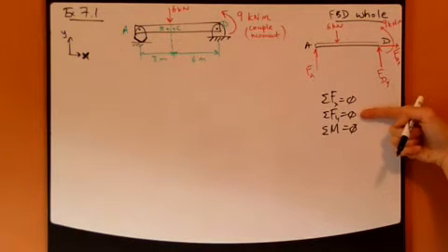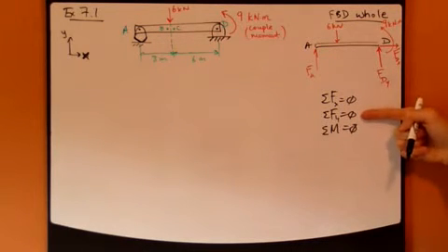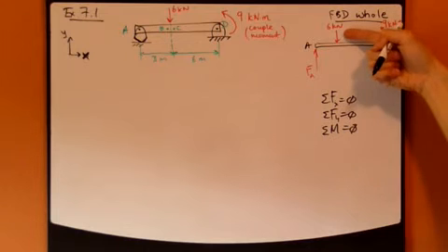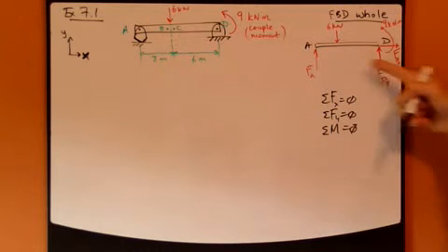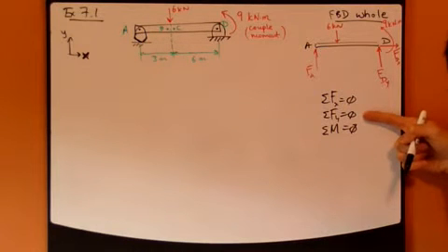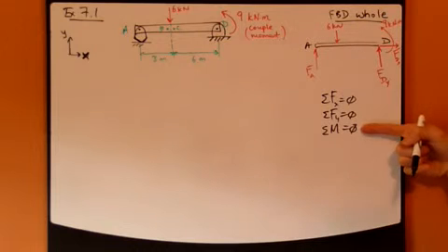Fy, the second equation, is useful. Well, okay, Fa will appear in this second equation right here, right? Okay, I know this, no problem. This will appear also, but I don't know Fdy. So there are two unknowns here from this equation. That's useless as well. How about this equation? From a moment equation. Now, this could be useful.